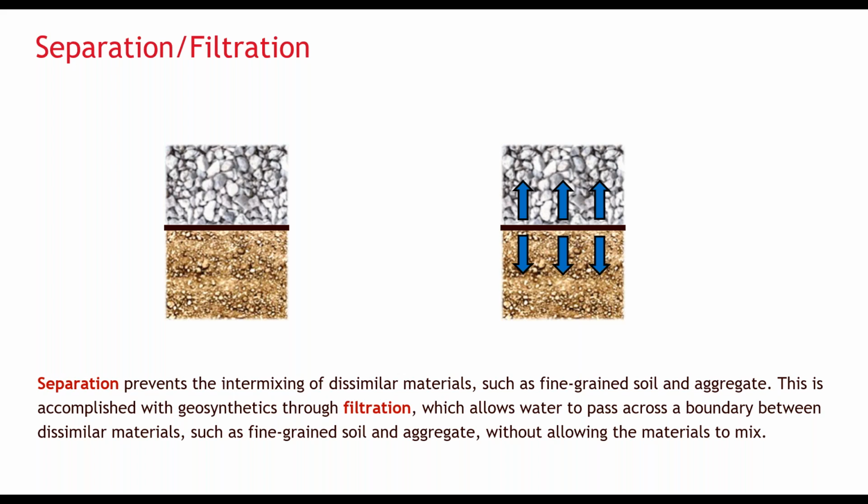With geosynthetics, there are a couple of ways we can go about this using either geotextiles or geogrids, but they achieve it differently. This is the source of quite a bit of misunderstanding because geogrid has large apertures. The fact of the matter is filtration is achieved differently with geogrid than it is with geotextiles. While a geotextile uses the geosynthetic material itself as a filter, a geogrid works with the aggregate particles which are confined in the apertures to create a filter.